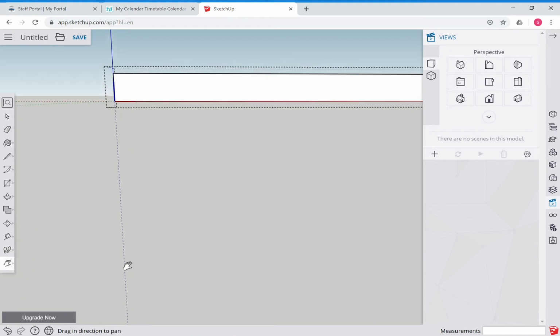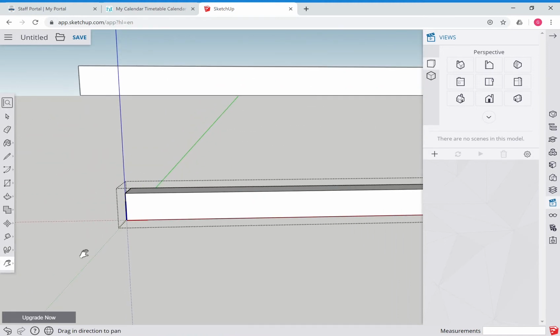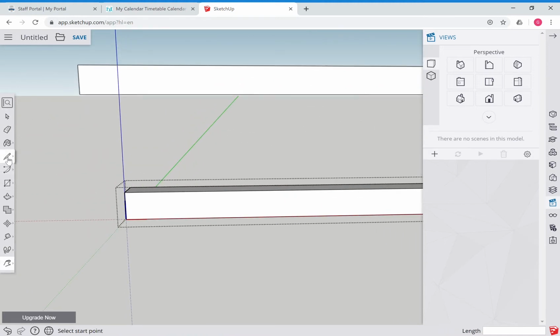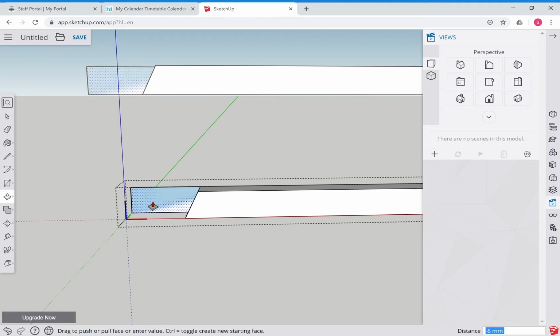Let's just get us so we can see both of them. If I get my pen tool and I do exactly what I did before and click, and then I grab my push-pull tool and I cut that, look what's happening. Okay, can you see both beams are behaving the same way? So if you want components that you want to change the same way, or parts you want to change the same way, you make them components rather than groups.